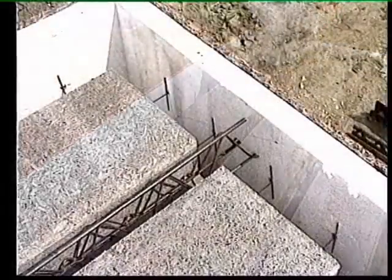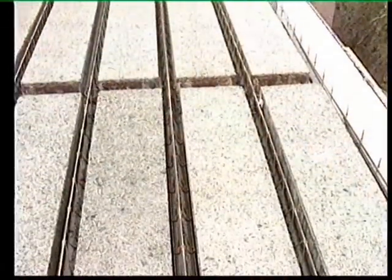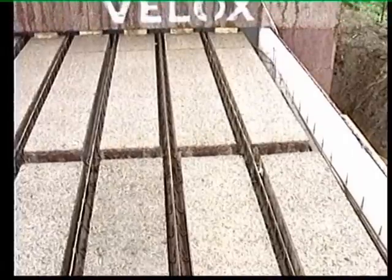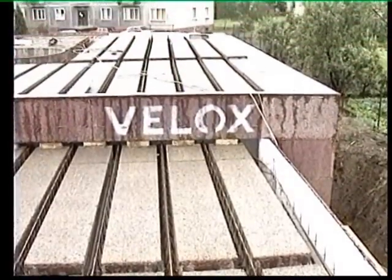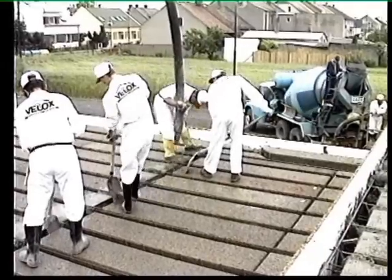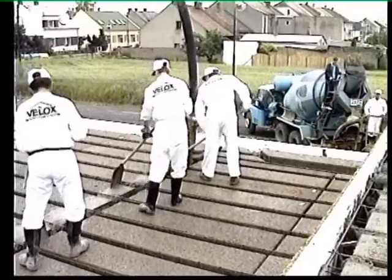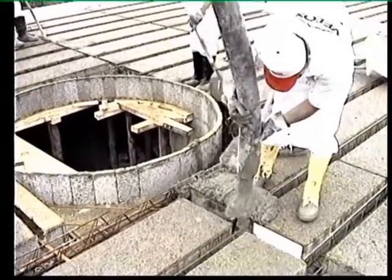After the horizontal leveling of ceilings, the first floor is prepared to be poured with concrete. The resulting boarding between the wood chip cement boards is either progressively filled with concrete from the peripheral walls to the interior walls by individual level, or, as in our case, the whole floor is built and the concrete is poured at a single time.